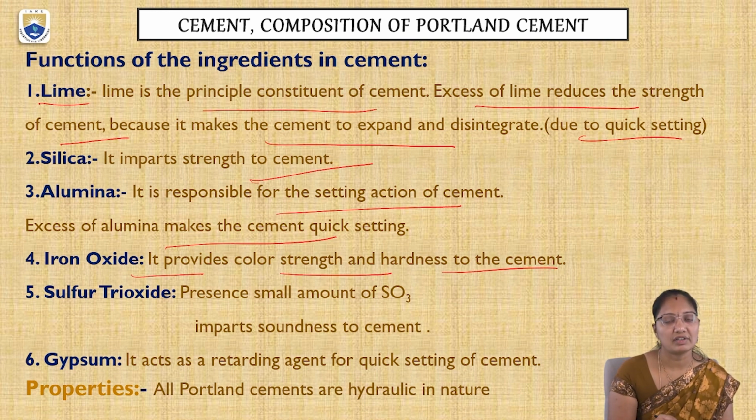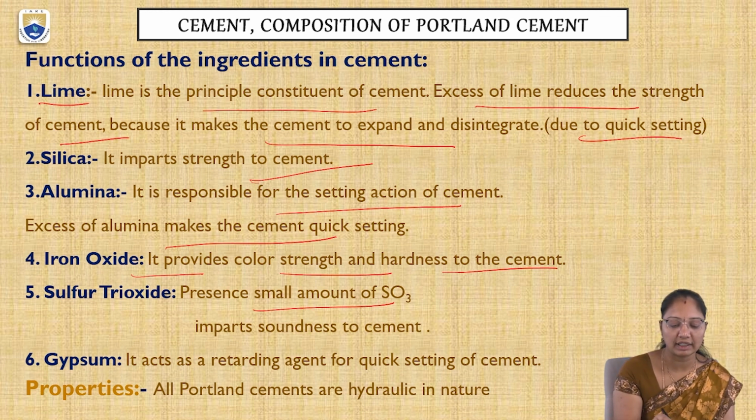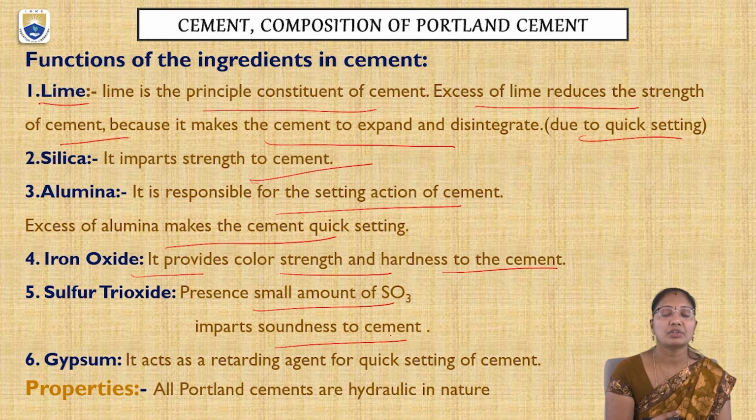Next, coming to sulfur trioxide, even the presence of small amounts of SO3 imparts soundness to cement. Soundness is nothing but the change in volume. Even with the reaction of water, it should not change according to the temperature. If we take the cement in a mold and maintain different temperatures, it should not change its volume. This is called the soundness of the cement. Then gypsum acts as a retarding agent for quick setting of cement.